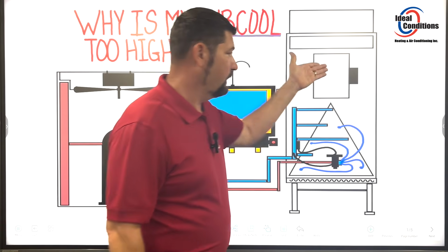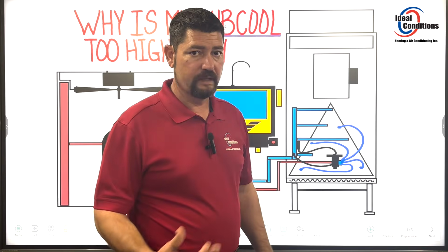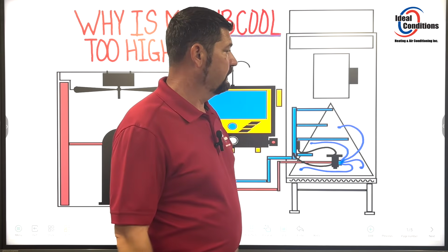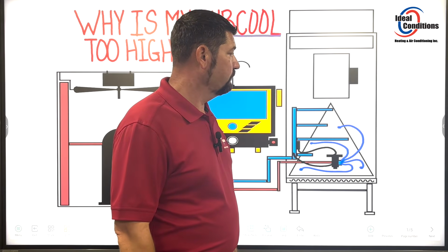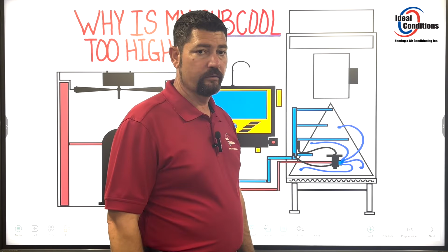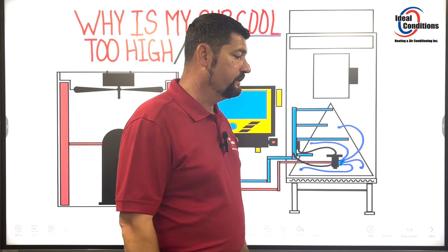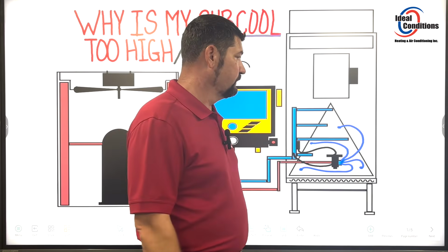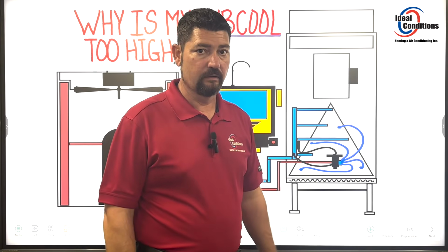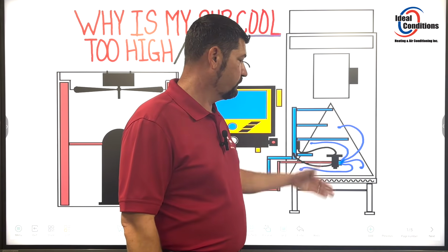Well, I was moving 400 CFMs per ton at 4 tons, it's giving me 1,600 CFMs of air, and that was maybe a 2/3 horse or a 3/4 horse or whatever. And what did you stick on there? A 1 horse. Okay, and then you put it on high speed. Now I'm moving 2,200 CFMs of air. Yeah. That's not going to really work very well.